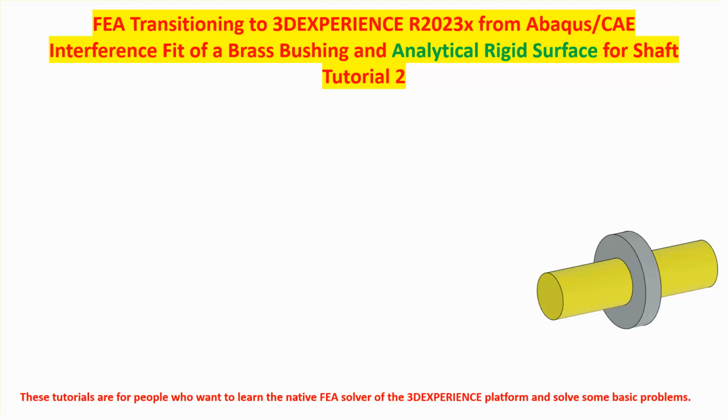Okay. So the second tutorial that I'm going to do today, I'm going to assume that it's an analytical rigid surface. The difference between the two of them is that in the first tutorial, when you assume it's rigid, I have to mesh it with something. For example, I used shell elements, and then I declared those shell elements to be rigid, in spite of the fact that when you mesh it with shell elements, you have to give it some dummy material, etc. So, for an analytical rigid surface, you don't have to mesh it.